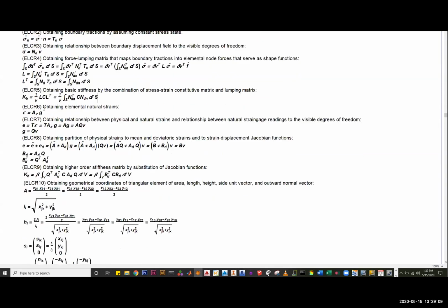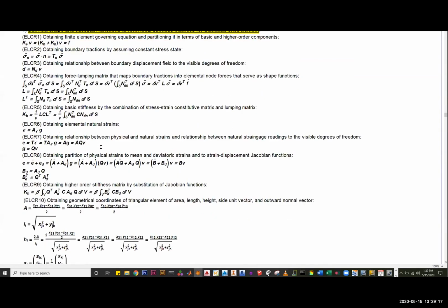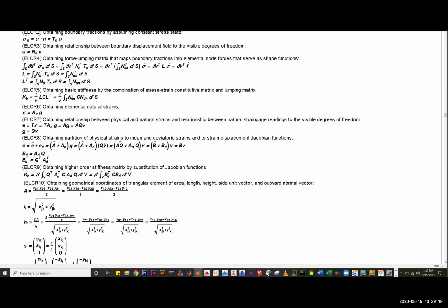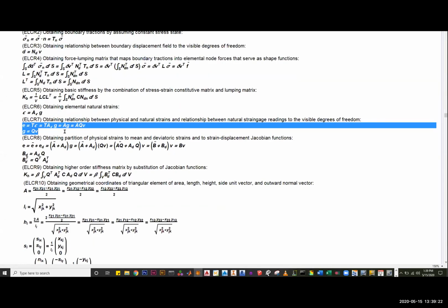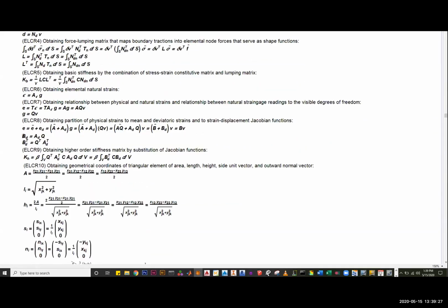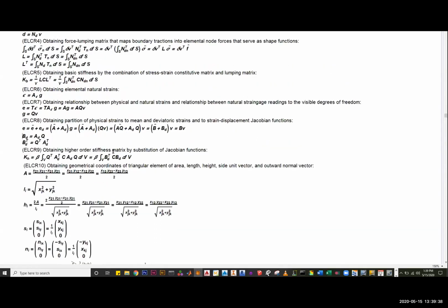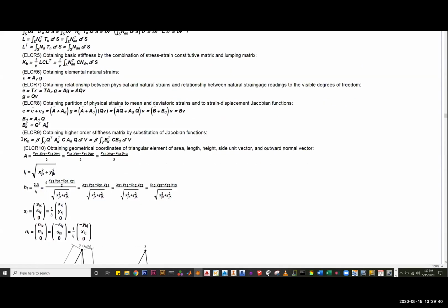Now what I'm doing here is finding the second stiffness, this higher order one. What this does, as I read, is it gives better performance. How you do that is all of this. In this KH term, you're going to get this strain, or the B matrix, which is like a Jacobian of your shape functions, or your strain gradient, your displacement gradients, your strains. And so this pops out. You're going to get this KH term with all these terms.